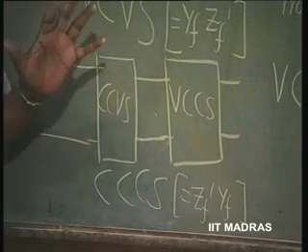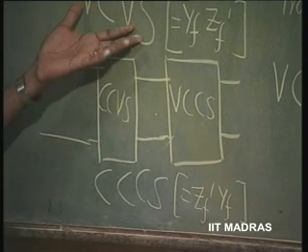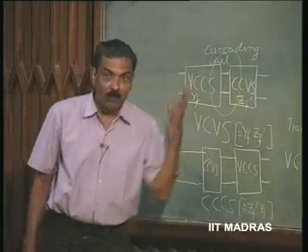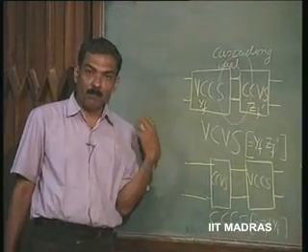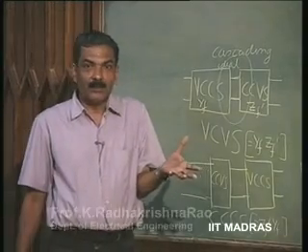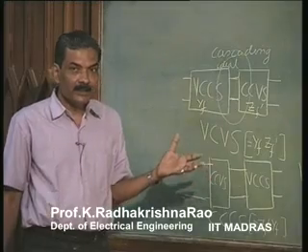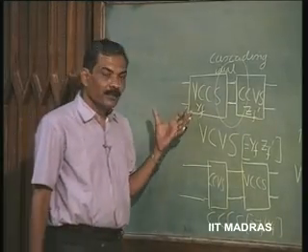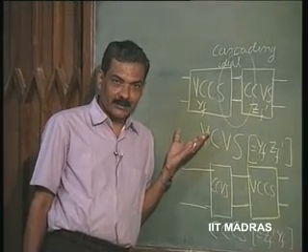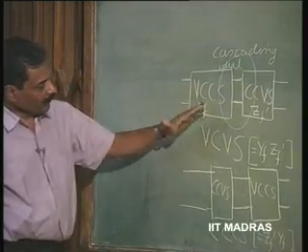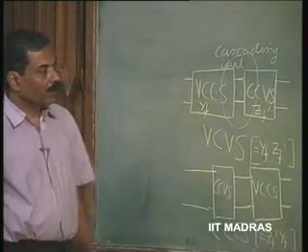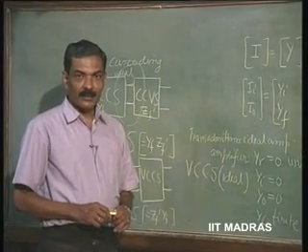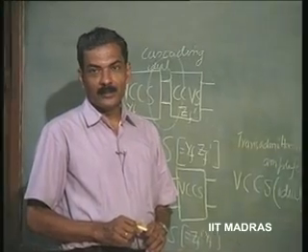So, one would say that it is enough if you have these two blocks realized, the other two blocks can be easily realized. Whereas, if you have only the other two blocks, these two blocks cannot be realized. So, these two are more basic than the other two, even though the other two seem to be more popular. These two, if you try to realize, it is possible to realize all the 4 types of amplifiers. So, it is necessary that these two must be studied and the possibility of designing these two optimally should be investigated, so as to not unnecessarily waste time on the other two designs. Right. So, we have voltage control voltage source realized this way, current control current source realized this way, and therefore, we could say that these two ideal amplifiers are more basic than the other two, which will be again discussed in terms of now what are the parameters.